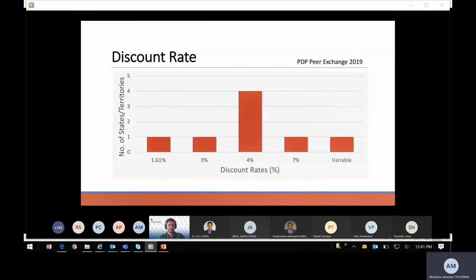Now, the reason that these pavement design manuals were reviewed by me personally is that FHWA is still in the process of reviewing the pavement design policy peer exchange itself. And because of that, its technical guidance for pavement design, including LCCA, is still under review. So FHWA's current guidance is still to go by discount rates set by OMB if you're not sure what to use. An online search of OMB discount rate will provide the information that you need for that. Next slide.